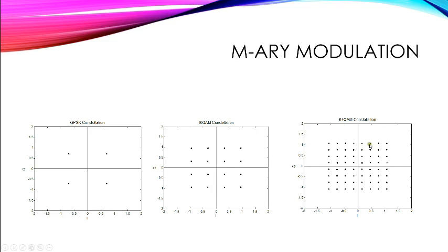But if we see the constellation for the 64 QAM, we see that the points are very close to each other, so a very small amount of noise will definitely cause confusion, and it will be very easy to make mistakes in the decoding when the SNR is low.